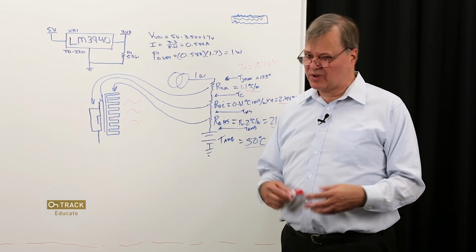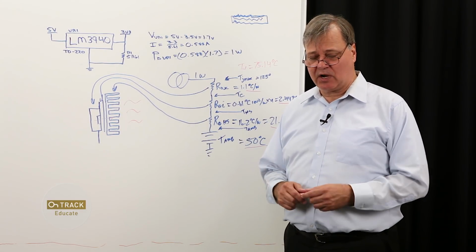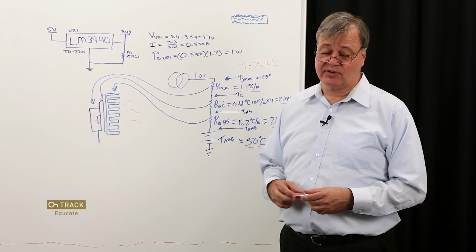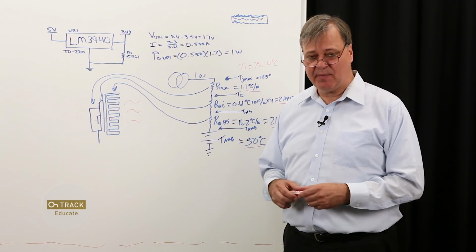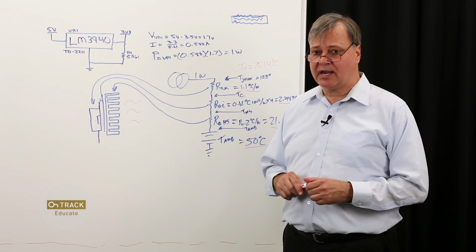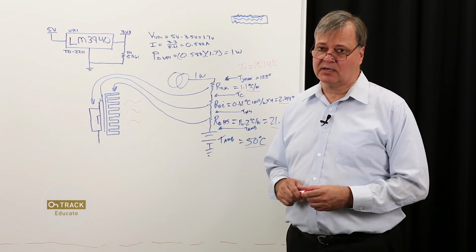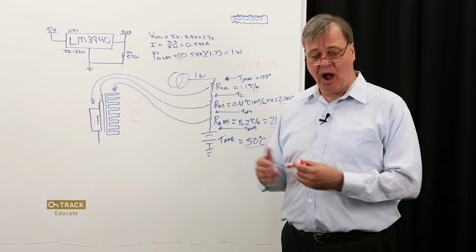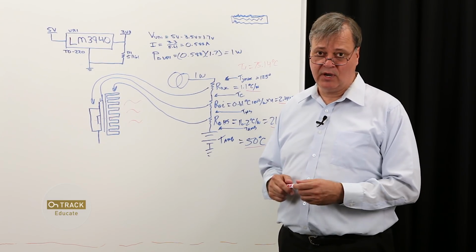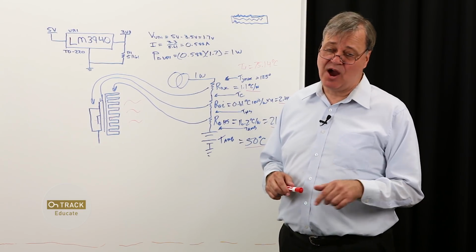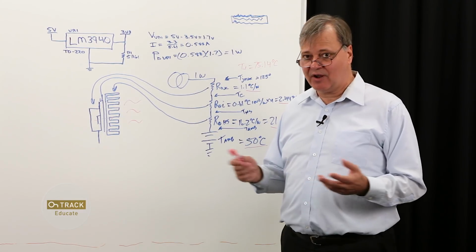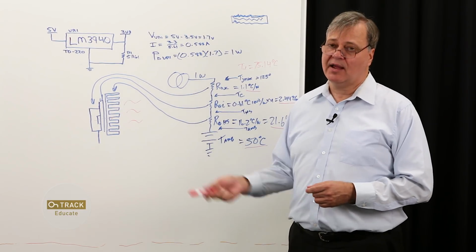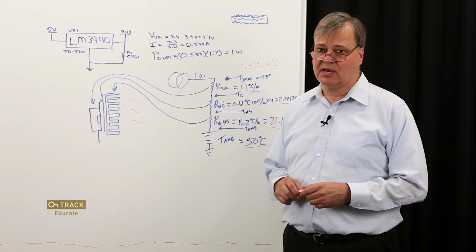But it begs the question, what's the right operating point? Well, that's a judgment call. In some applications, you'll have a specification on your thermal derating of all of the components in your design. If you don't have that, then you kind of have to make a judgment call, keeping in mind that the reliability of an electronic product goes down with the square of the temperature. So what that means is if I double my operating temperature of all of my components on the board, then my reliability is going to go down by a factor of 4. Kind of comes down to, how long is a string? What's the right value? Again, as engineers, we need to make that judgment call. And this is a calculation that needs to be done for every component in your design.